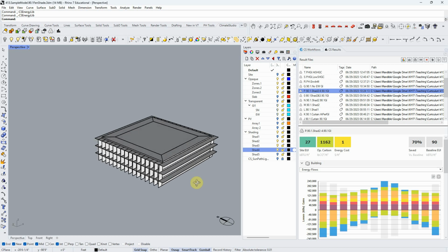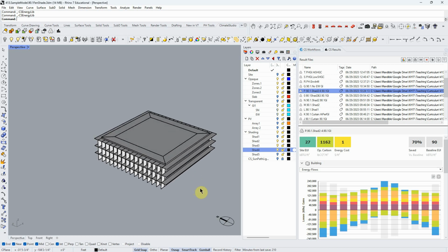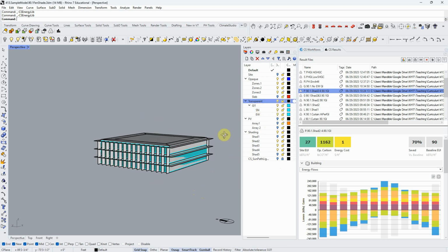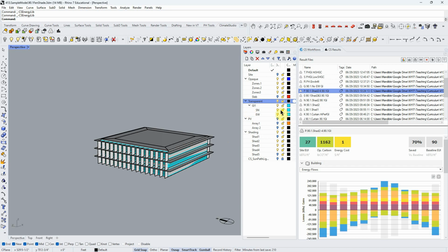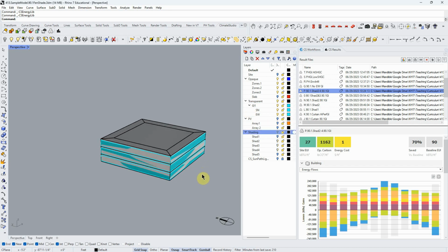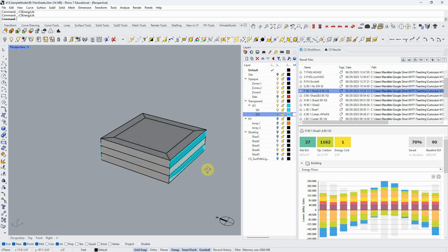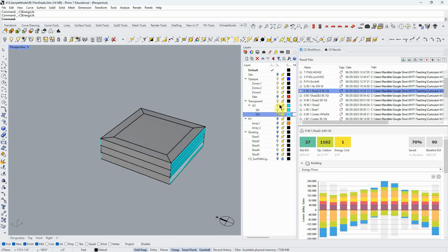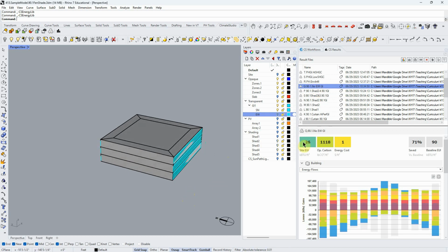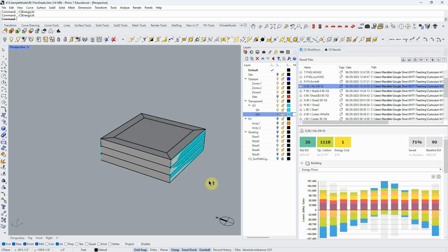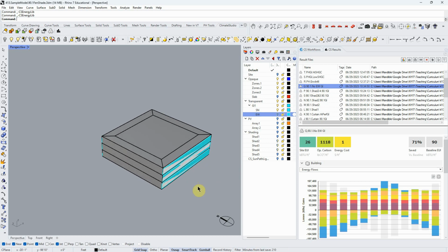But then I said, well, another way to prevent heat gain on that glass is to get rid of some of the glass. So I took out the glazing on the east and west side. So right now I've got glazing all the way around. Let me just turn off the shading. So then I said, okay, what if I just get rid of this glazing on the east and west, have north and south, and then without any shading at all, I'm down to where I was before too. So I can shade glass. I can adjust the amount of glass.